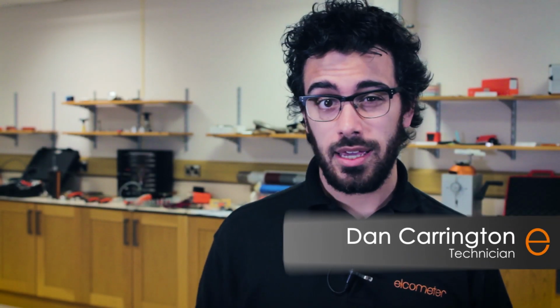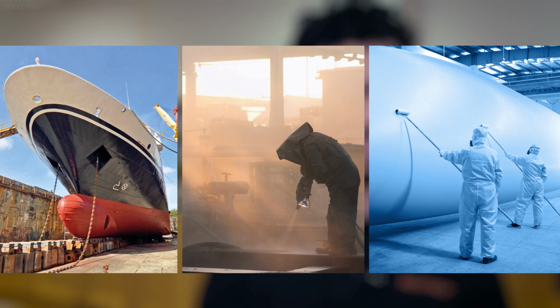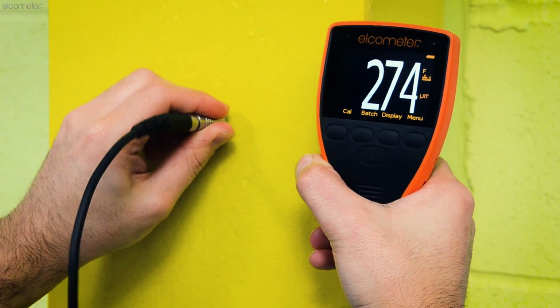When it comes to applying a coating, whether in a shipyard, a construction yard, or even in a warehouse, even if you've successfully controlled and monitored the surface cleanliness, surface profile, and both the wet and dry film thickness, if the climatic conditions are wrong at the time of application, this could cause the coating to fail, regardless of the success of the other parameters. That's why it's vital to monitor a range of climatic parameters before and during the application process to ensure your coating can have a successful service life.